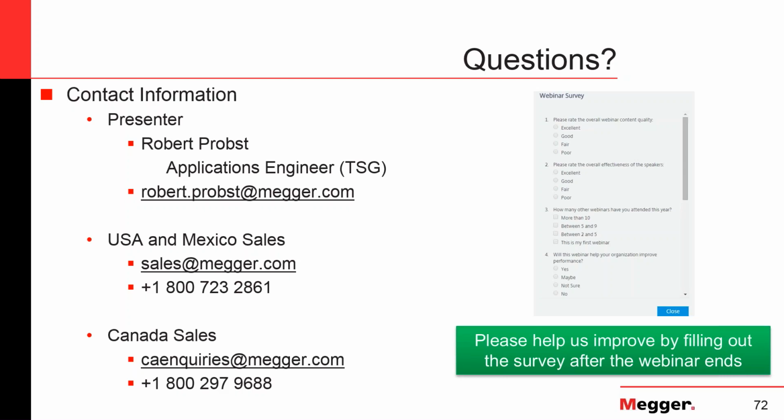Another application would be just to check the entire protection scheme, not just the differential. You inject current through the primary of the CT, which is the bus, and then the CT will pick up. It will feed that into the relay. The relay hopefully has the right settings and will trip the circuit breaker.